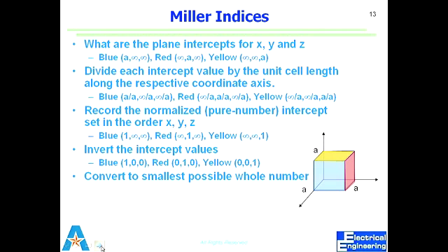So is this as simple as saying that 100, 010, 001 are the vectors defining the normals to the surface planes? Yeah. And we call it a plane. So what plane is this wafer? You'll tell me it's 100. That's all I need to know. So it's the x plane. How about 110? We'll get to that very soon. Let me make sure this sinks in with what we have right now.